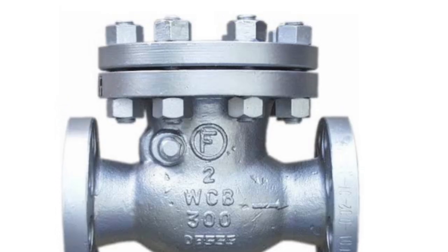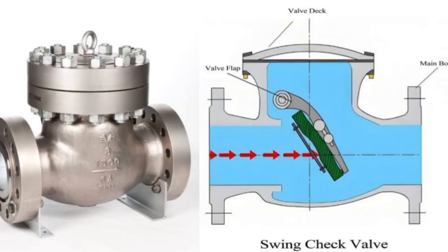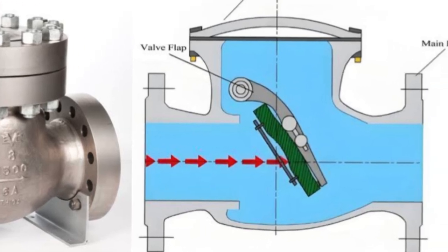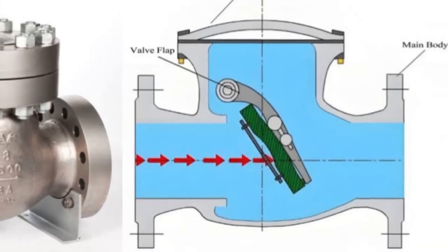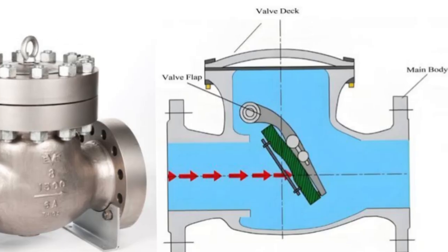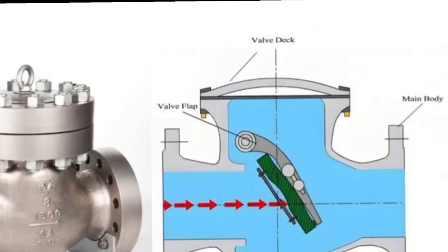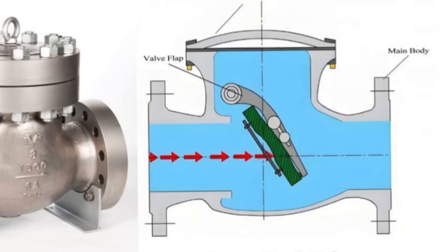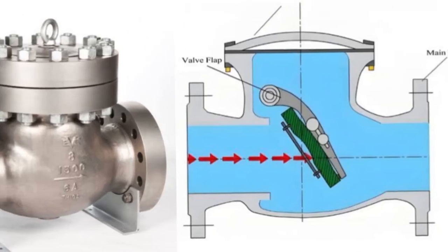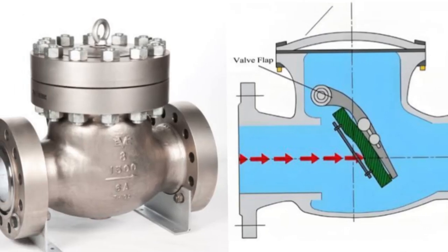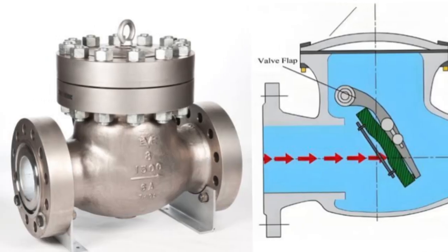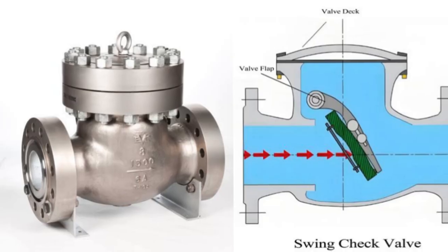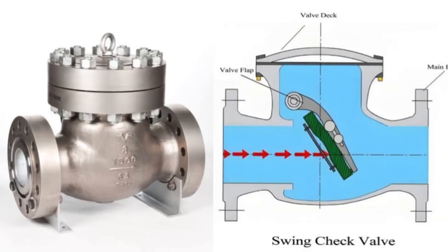In steam systems, check valves are used to stop reverse flow, protecting boilers and piping. In oil and gas lines, they prevent pressure from flowing back, which could damage pumps or cause leaks. In slurry lines, check valves are used sometimes, but they need to be heavy-duty types because the solids can damage the internal parts. Check valves are used where backflow must be avoided and systems must stay pressurized in one direction only. It's used commonly at pump discharge.